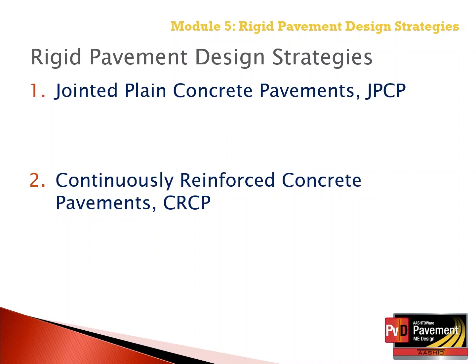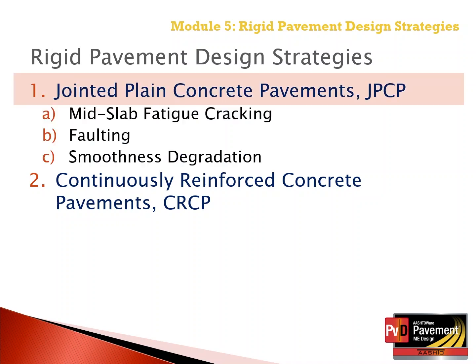We will start with the JPCP rigid pavement design strategy and will overview the three distresses or performance measures used for designing JPCP. The three distresses or performance measurements include mid-slab fatigue cracking, faulting, and smoothness degradation or IRI. Continuously reinforced concrete pavements are covered under Module 5.2.